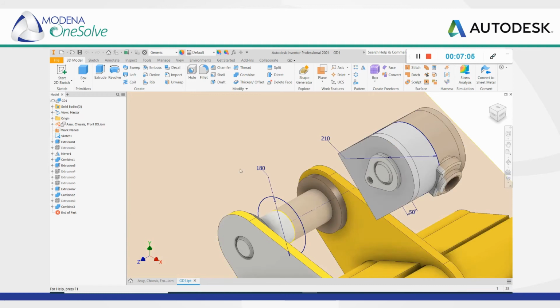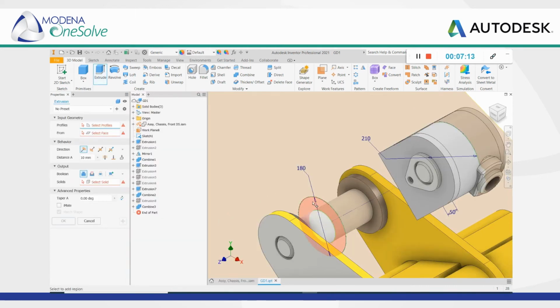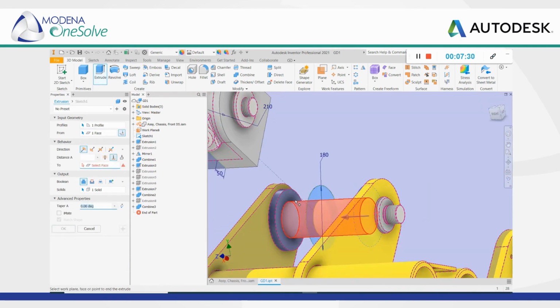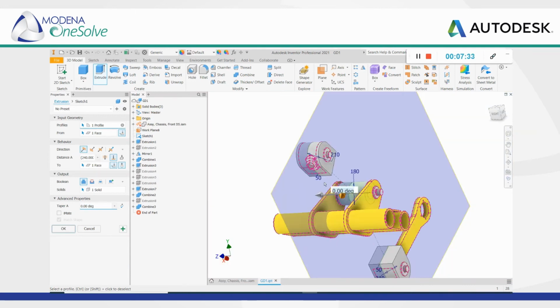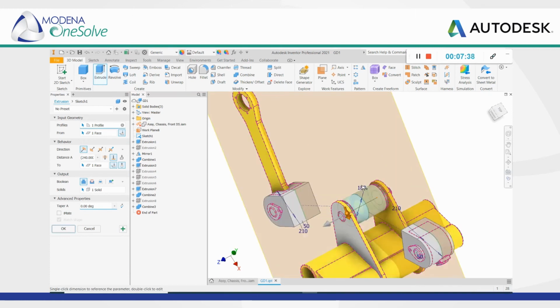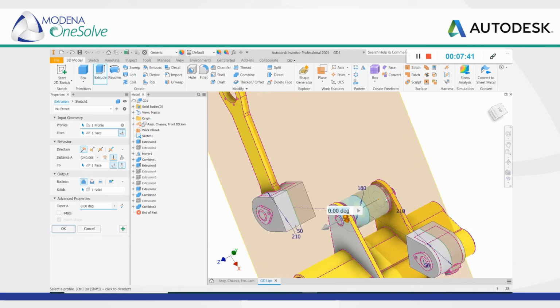Okay, so what's going to fit around this axis? It's going to be a solid body, and I can design that relatively quickly by running an extrude. Okay, so that component's going to extend from this face, and it's going to go all the way up until that point over there. And let's just rotate this a little bit. Zoom in. Okay, so I've made a design change, so I've added some preserved geometry.